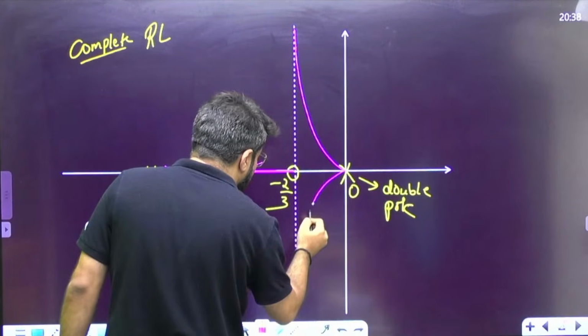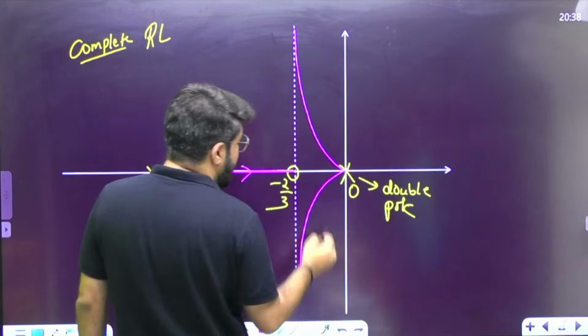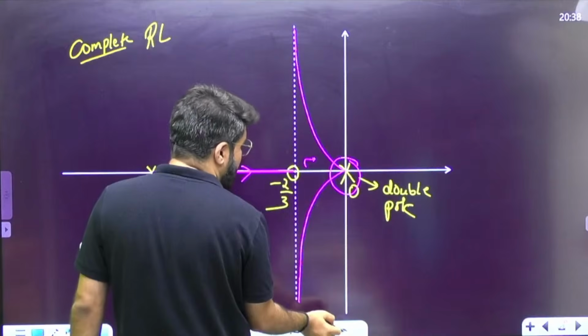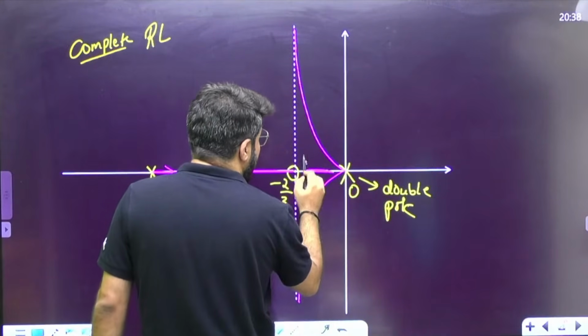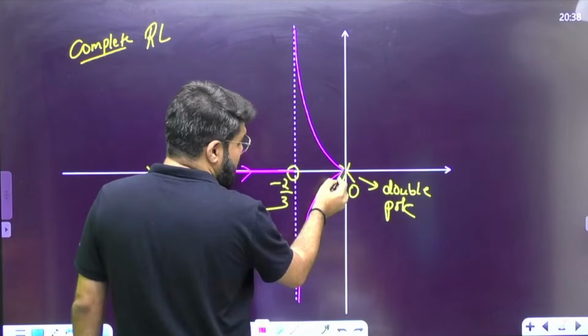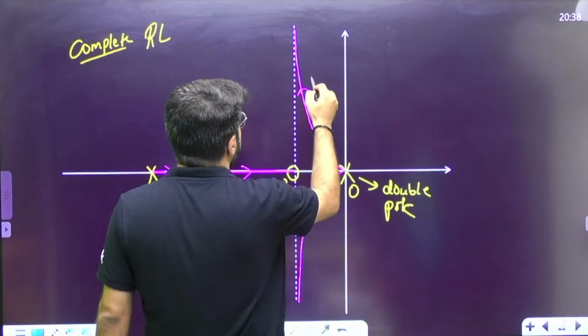If you apply the odd number criterion I told you, you will find that the root locus cannot exist here, because if I look to the forward side, I have two poles. It is not a single pole, it is a double pole. That is why, if you see an even number of poles on the right side, the root locus cannot exist here. So directly from this pole and this pole, this is how root locus branches will terminate.